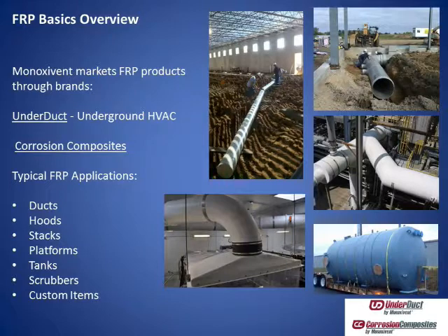At the bottom of the scrubber you'd collect in the sump, say, ammonium sulfate, and when the pH gets to a certain point, then that goes off to the wastewater. And they run continuously, and scrubbers can typically do 98, 99% removal of the element they're trying to remove. So they're rather common in industry and in wastewater.